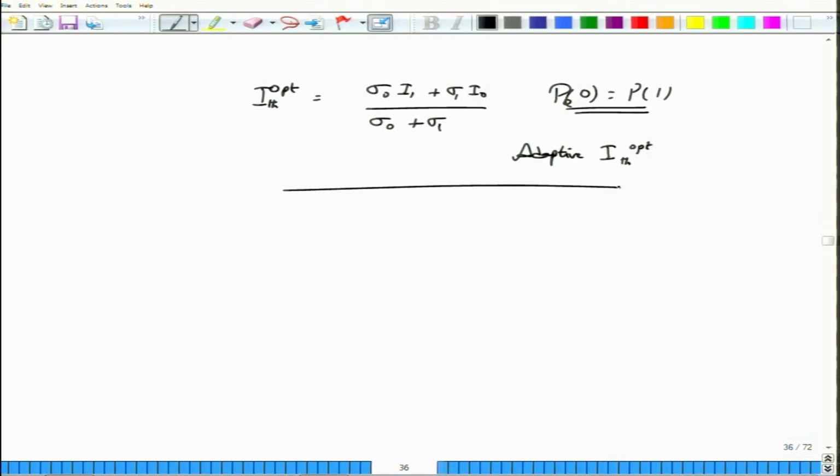So, this is the case that we have seen for the simple direct detection for the on-off keying when we had no preamplifier, and the most important lesson that you need to learn when there was no preamplifier is that when you launch a bit 0, if the extinction ratio is not 0, P0 will be non-zero, which means I0 will be non-zero. So, there will be a small amount of shot noise, but usually that shot noise can be neglected in comparison with the thermal noise that is present. So, I0 can be approximately taken to 0, if not you have to modify the equations only slightly.